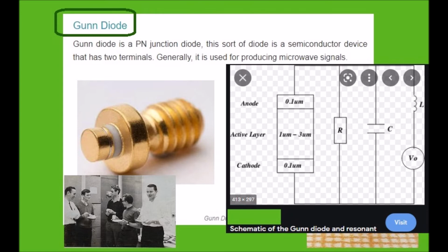When a voltage is applied to the device, the electrical gradient will be largest across the thin middle layer. If the voltage is increased, the current through the layer will first increase, but eventually at higher field values, the conductive properties of the middle layer are altered, increasing its resistivity and causing the current to fall.